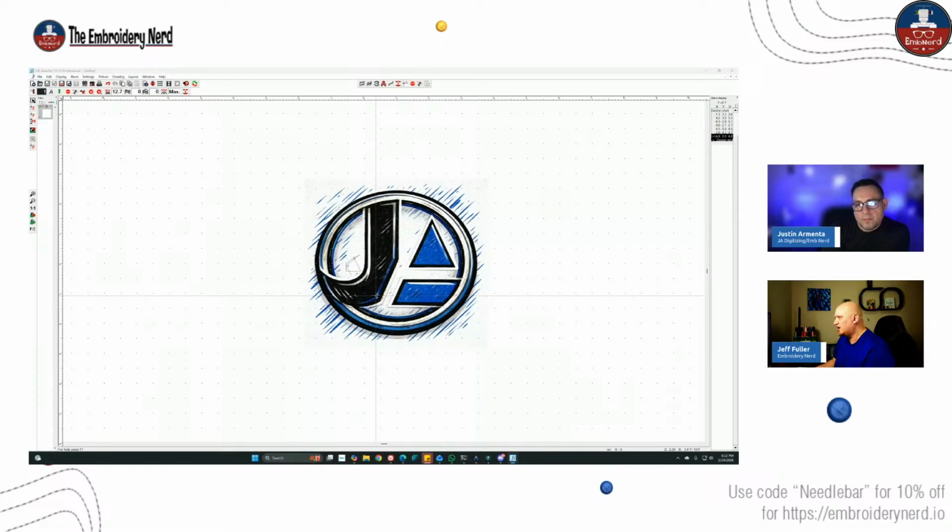So I can back those up, but basically, once you put down that first point, it's almost like dropping a needle penetration. But I backed it all the way up there just by hitting the backspace key because I wanted to change the needle. So as you can see, I put a needle change in there. Now we're starting with needle number 2. And I'm just going to come over here and click, and that's going to drop that needle position.